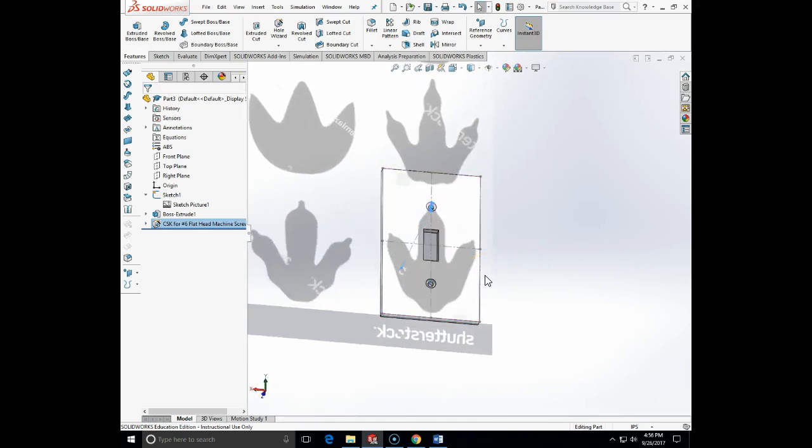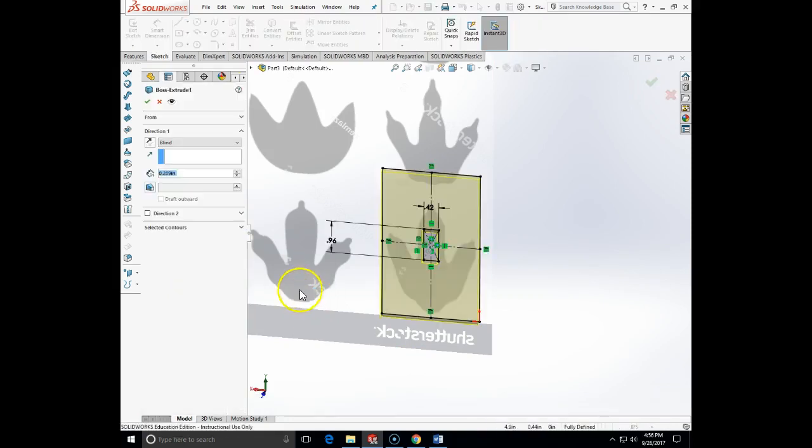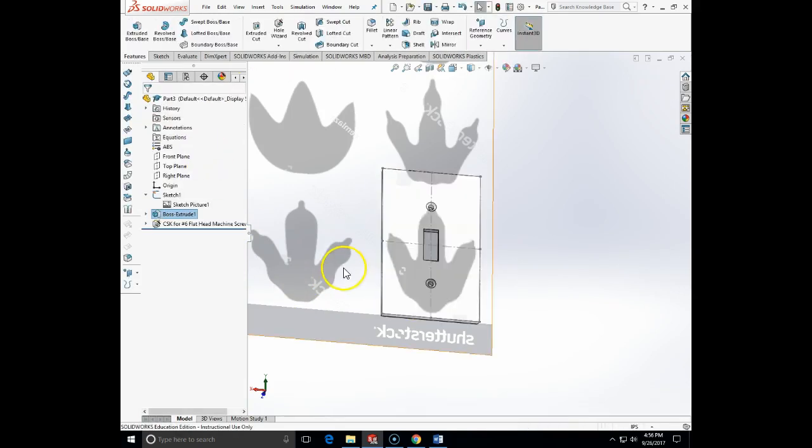And after I'm done with the shell, I'm going to build the ornamental feature of the dinosaur paw. Because if I do it otherwise, it will not work, because the shell will try to also shell the dinosaur paw, and that will lead to a shell collapse because the minimum thickness and radius will not be able to be enforced. Also, one other thing I may want to do here is introduce a 5 degree draft, as in the next exercise we are also going to make a mold.